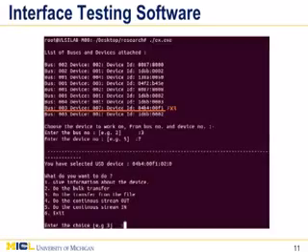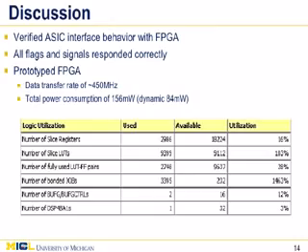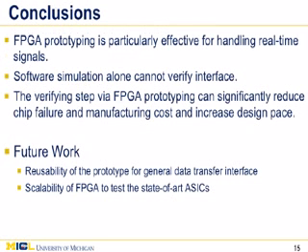The prototype on FPGA using Spartan 6 shows data transfer of about 450 MHz, which is fast enough for the desired performance, and total power consumption of 156 mW. The figure shows the number of sliced registers, lookup tables used, and device utilizations. By prototyping ASIC with FPGA, we can ensure the functionality of the circuit, while software simulation verifies the logic, but often it cannot verify in real time. Because the stereo vision hardware accelerator runs in real time, verification is extremely important. This step can reduce chip failure and thus manufacturing cost.